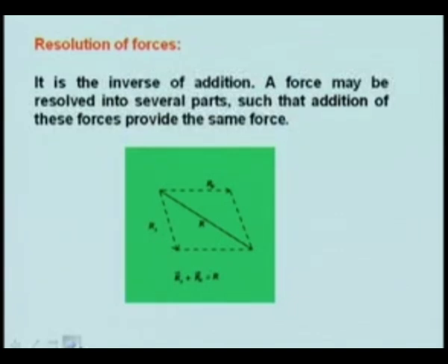Then we discuss the resolution of forces. Resolution is the inverse of addition. Like two forces can be added to make the resultant, similarly, a force can be resolved into two components or several components such that the addition of these forces provides the same force. Whereas the resultant of forces is a unique vector, resolution of a force may give many solutions. However, if we fix the directions, then you may get a unique solution.